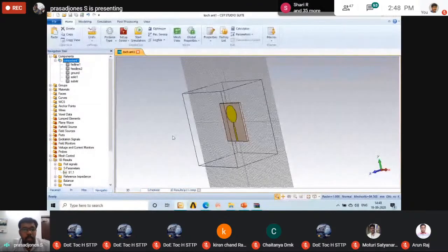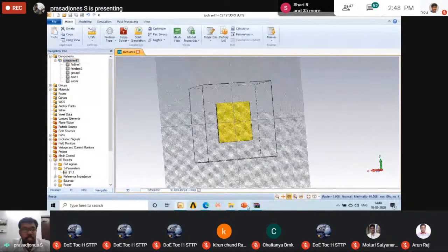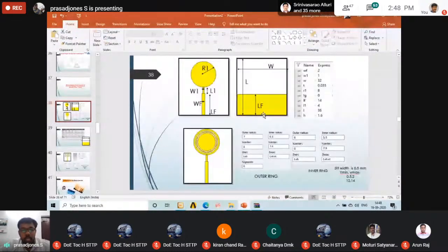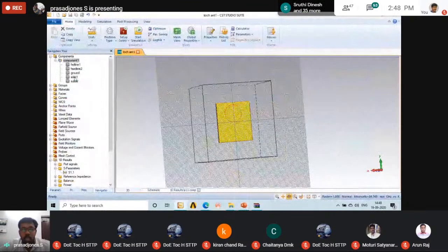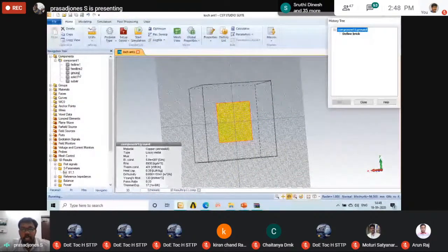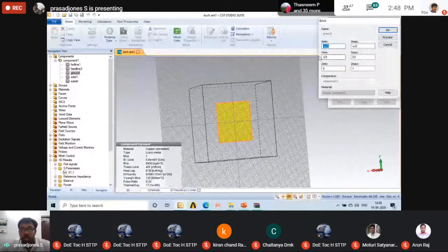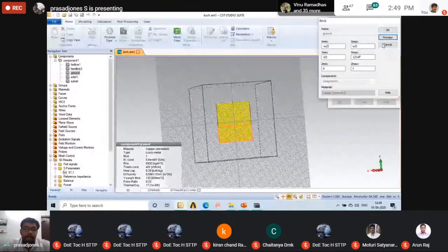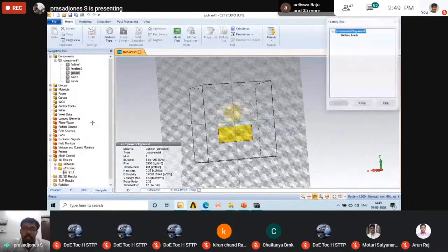So what I'm going to do is design this antenna, where the length of the antenna is equal to L. For that, I'm just double clicking on ground, and again I can edit the list. So from minus L by 2 to minus L by 2 plus L. On previewing it, you can clearly see that the ground is reduced. Click on OK. Close it.